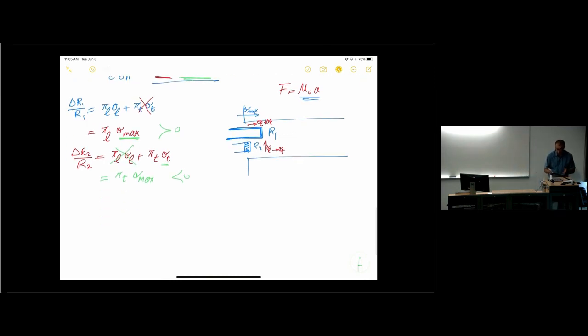And the question says, how can we make a circuit to maximize the signal? Well, here is one possible solution. So let's say if this is R1 and this is R2, you can apply your source here. You can apply a constant voltage source or a current source and measure the other parameter. But if you put these resistors in series like this, because R1 goes up and R2 goes down, this gives you the maximum sensitivity. This circuit gives you the maximum sensitivity.